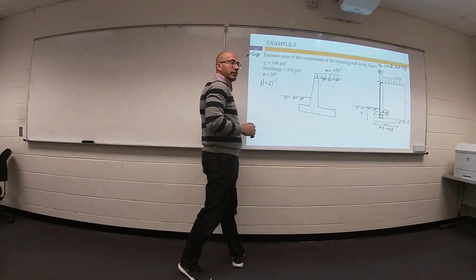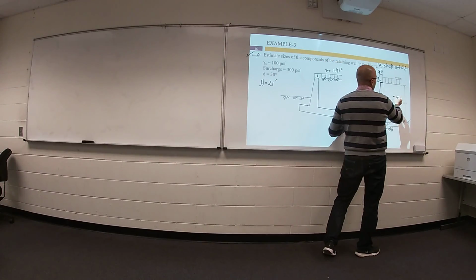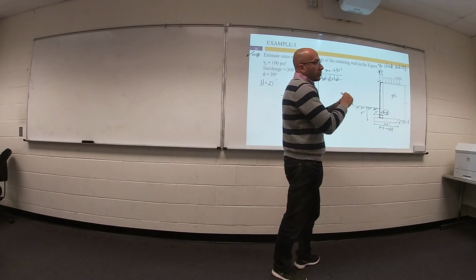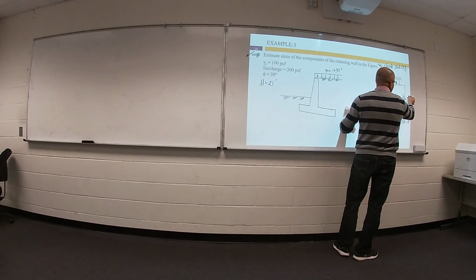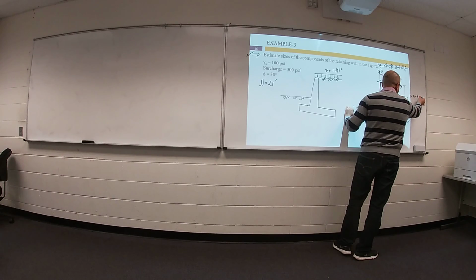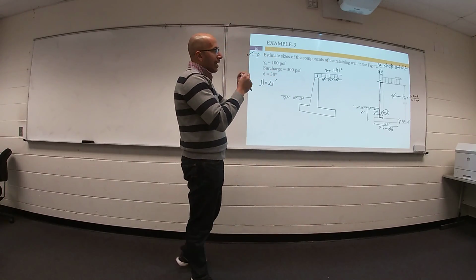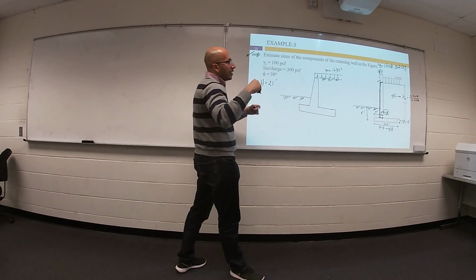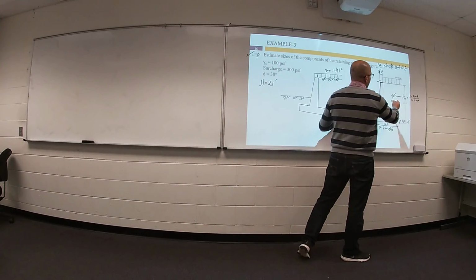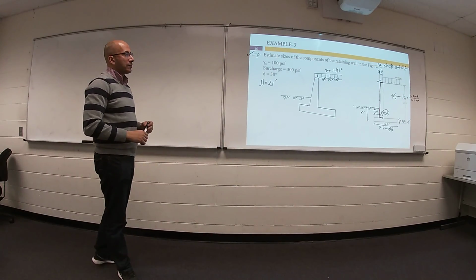Dr. Emin, where does that angle come from? Which angle? The 30 degrees? Phi, the interlock or the friction between particles of the soil. This phi is important to figure out the K active value, 1 minus sine phi divided by 1 plus sine phi. If you have sand, between the particles of the sand we have friction in between. This friction can construct a relationship, and based on this relationship, I can figure out the value of phi. And that would come from a geo report or something? Yes, soil mechanics.